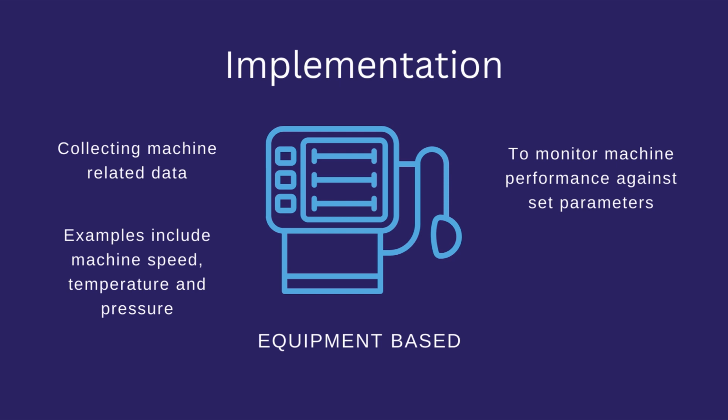Equipment monitoring allows in-depth analysis of the machine's performance, working, current status, and production records. An example is predictive maintenance, which continuously monitors different components of the machine and their variables such as motors, oil, gearboxes, and different mechanical structures. The software constantly monitors these variables to predict breakdown by the built-in algorithm. Other parameters specific to equipment include breakdown, faults, and alarms.